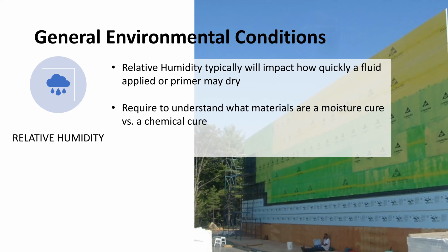Okay, so if you think of something like a spray foam, typically they'll have a condition of, don't spray at 90% and above relative humidity. And because they say that, what can happen is you can actually change that chemical reaction. So you might think, hey, it's nice out, it's sunny, I'm going to just spray this, but it's super, super humid. The foam just isn't going to set up as properly.